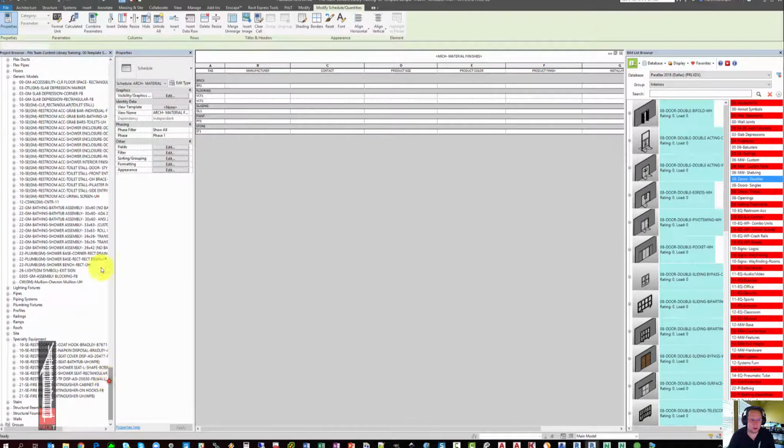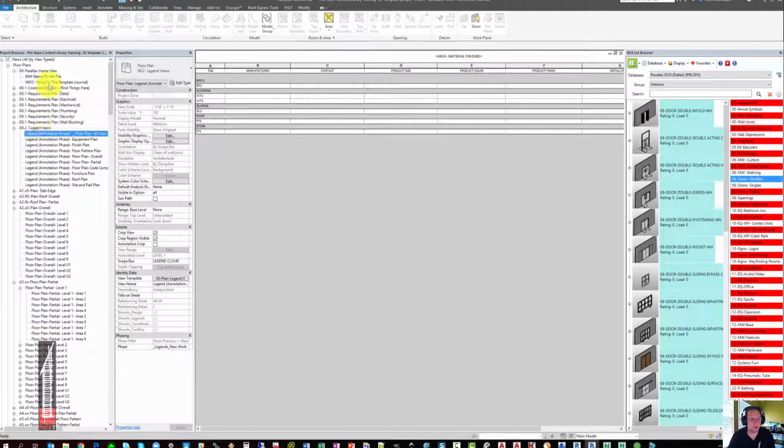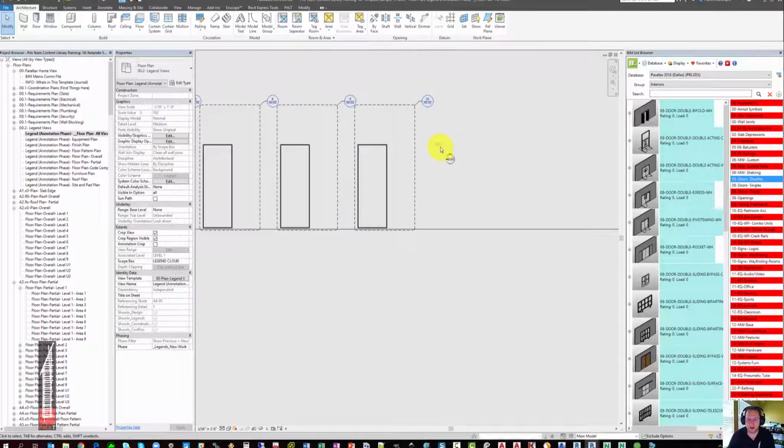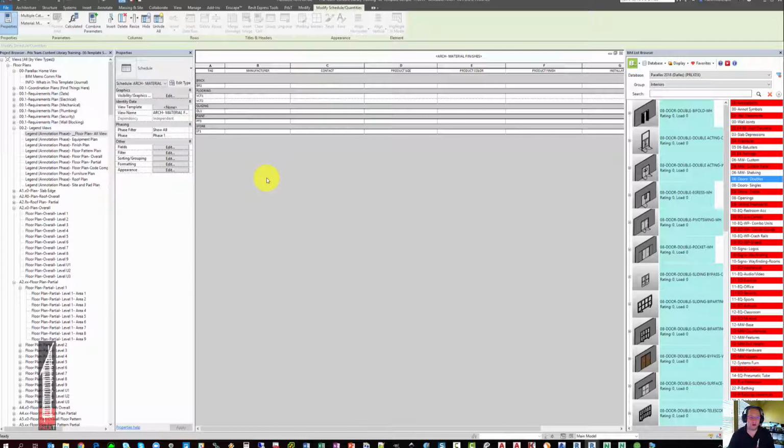In these cases, a workaround is often to go to a floor plan or a legend floor plan of the project and to model a small floor over to the right of the legends that does not actually interfere with the model. Then you can use the Revit Paint tool to put the material that you would wish to see in the finish schedule on that floor, at which point it will then actually exist in the model somewhere other than in a Revit wall sweep. Best practice is to leave as many materials in the schedule reading solely off the actual building model and to only use the floor workaround for the materials that will not schedule themselves.